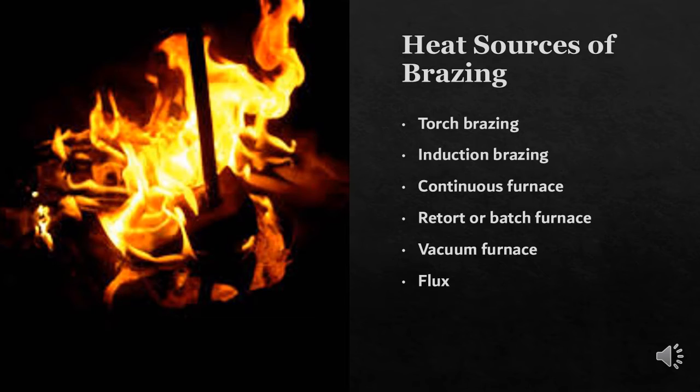Retort or batch furnaces can be refractory lined and heated by gas, oil, or electricity. Vacuum furnace means a furnace with electrically heated elements that surround the workload and heat the brazing filler metal to the liquid state, so the flow and the capillary attraction are achieved. However, vacuum brazing has limited application for copper, phosphorus, and silver brazing alloys. And the last is flux. Flux is the key to good brazing practice, and many problems arise from the incorrect selection or ineffective application of flux.